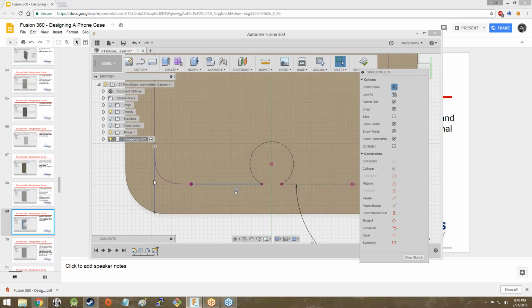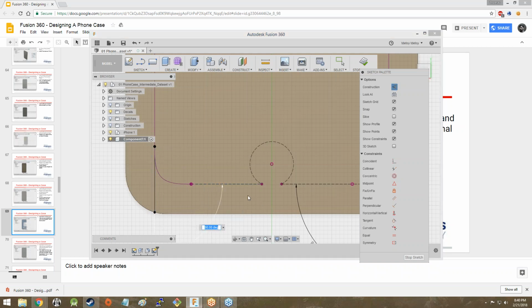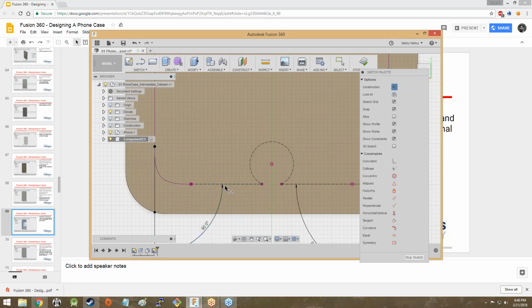All right, so I'm going to go ahead and sketch dimension again. That might be part of it too. There might have been a line created with the sketch dimension that overlaps it, or you may have used the sketch dimension to compare the overlapping line. In which case, if your sketch dimension disappears, that's okay. You can just redo it.